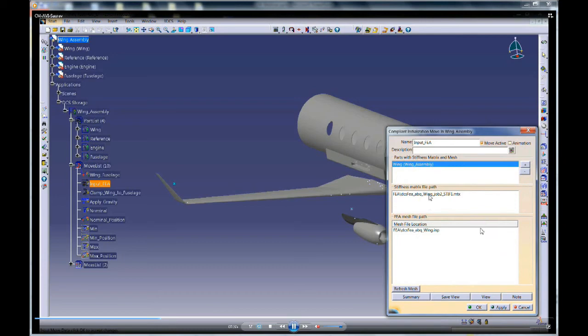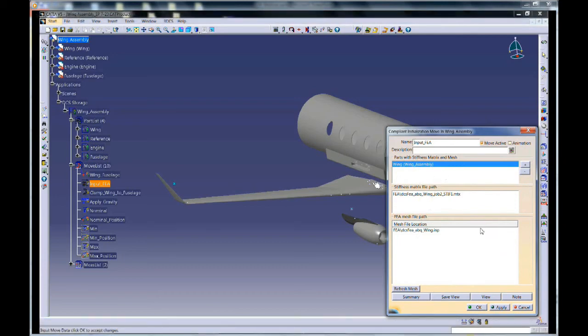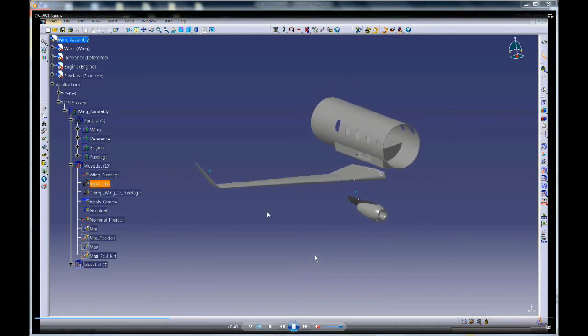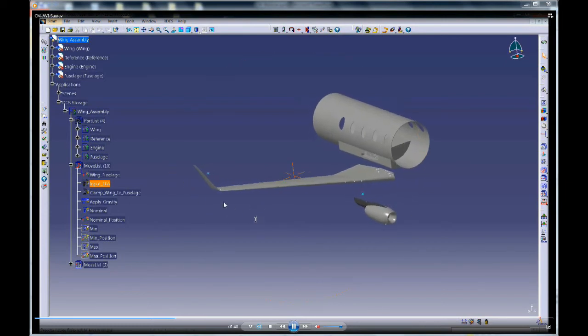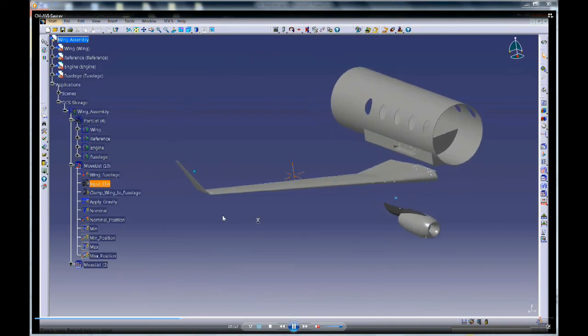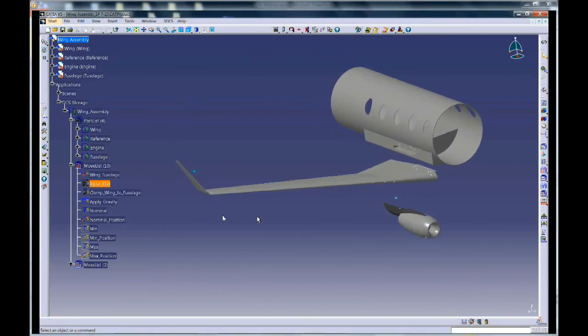That move is used to input the mesh and stiffness files we create using DCS StiffGen. And after we import the mesh and stiffness files, now these parts are compliant. So we need to import a mesh and stiffness file for all the parts we want to be compliant.